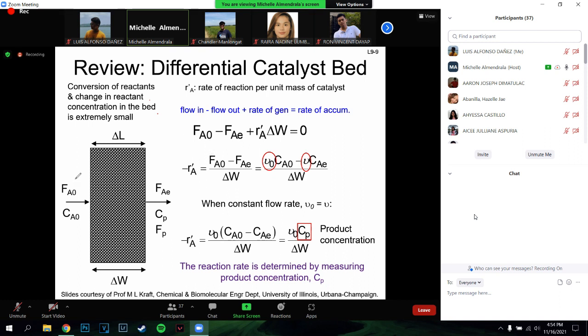So this is the flow rate of A, the balance, and this will be the concentration of AE. Now E represents the equilibrium concentration after the reaction, that is, at the end of the reaction: the remaining A, the concentration of A at equilibrium, the flow rate of A at the end of the reaction. So whatever the concentration of A inside the packed bed is the same as the concentration leaving the reactor. And therefore, there's a reaction inside the packed bed.